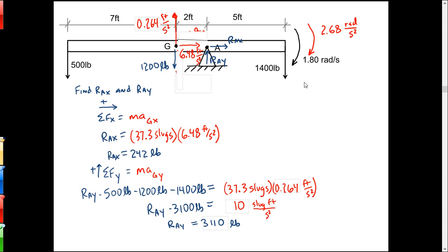And then once you've got that, it's just F equals ma again, is all it is. So kind of compartmentalize it when you go through it. Find alpha, find how the center of gravity accelerates, because it's rotating about a given point. And then once you've got that, draw that up nice and clean, and then F equals ma after that, okay?